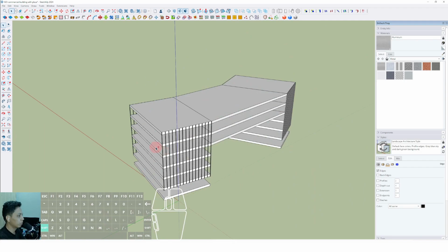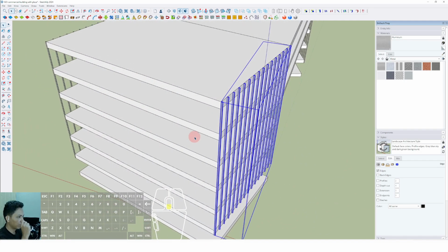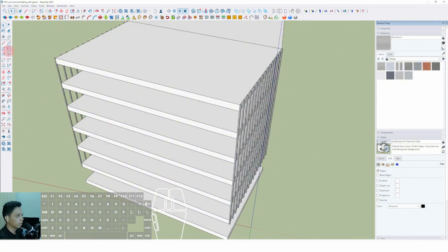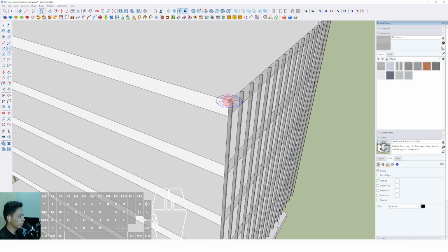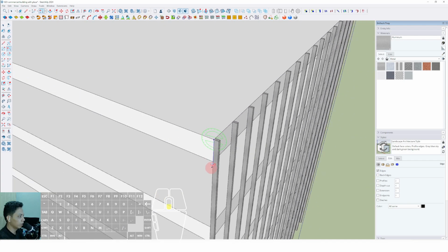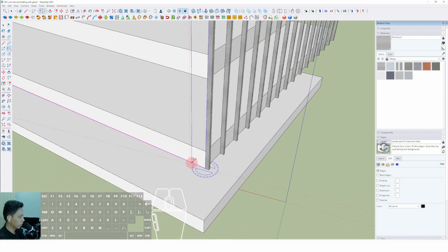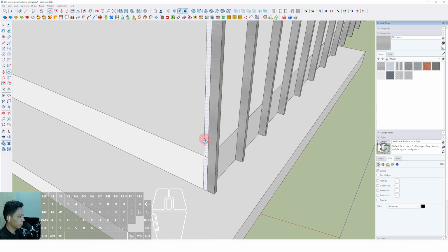Okay, well, now we can select this one again, or maybe we can make another vertical frame. Click the rotated rectangle, click in this position. Okay, we can click from this point, then click to this point, then we can set the height around 100 millimeters, then push it to the front around 200 millimeters.